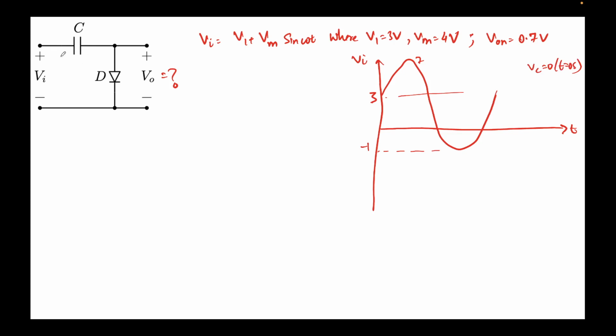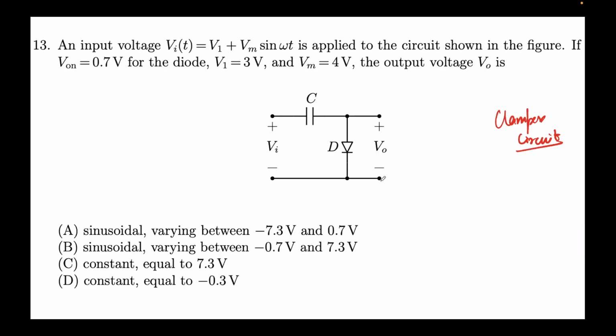So when it starts, a current will start to flow. This capacitor will get charged to a certain extent, and we'll assume that since the internal resistance of the diode is 0, charging will be instantaneous, right? So tau RC would be 0. This means instant charging. Right. So now if I draw V out, that is what we are required to find.